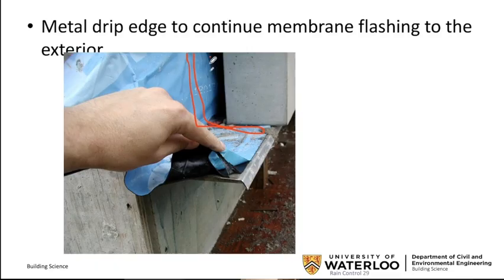So in this condition of going from vertical to horizontal, these membranes are really useful because they're not very stiff. And so when the temperature changes, they will stretch a little bit to deal with expansion and contraction. Because they're adhesive, you can lap two pieces together. Whereas the steel you see right here, that piece of metal comes in lengths of only 12 feet because it's rigid steel.